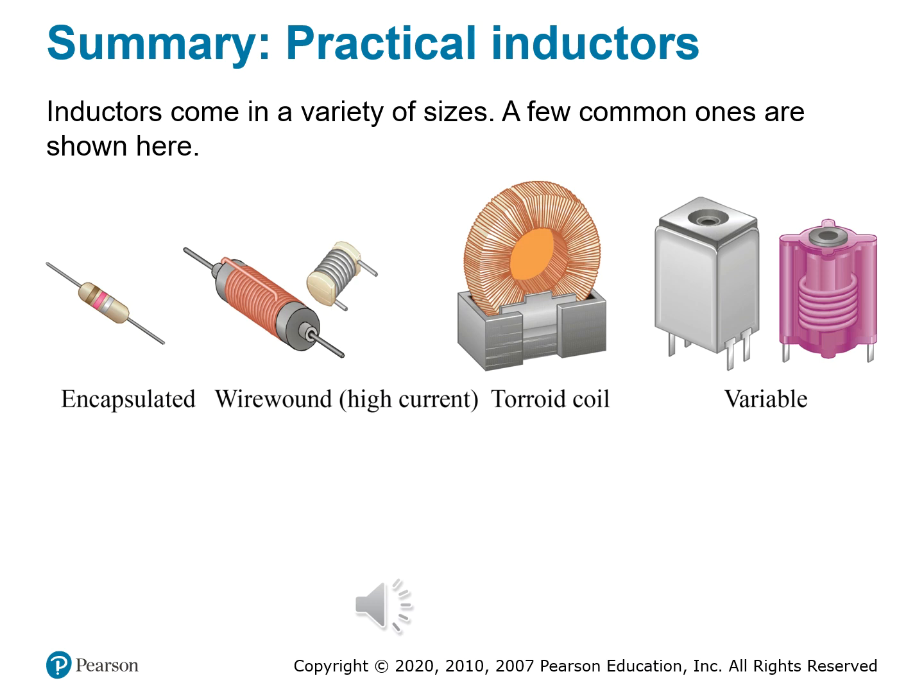Then we also have, as usual, the variable inductor. And this has a movable core, or what they call a tunable coil. You can just adjust the inductance by rotating a screw or sliding some ferrite core. These are found in oscillators, tuners, and radio frequencies where precision matching is needed.